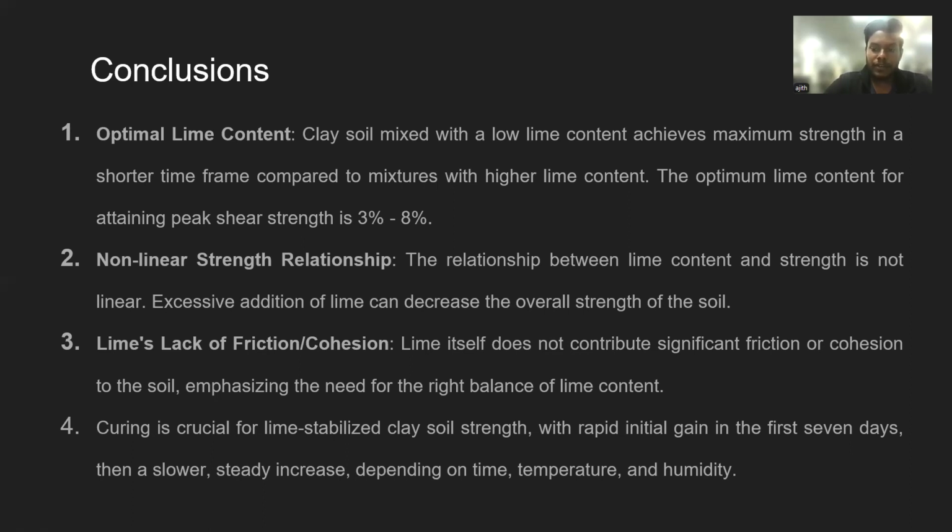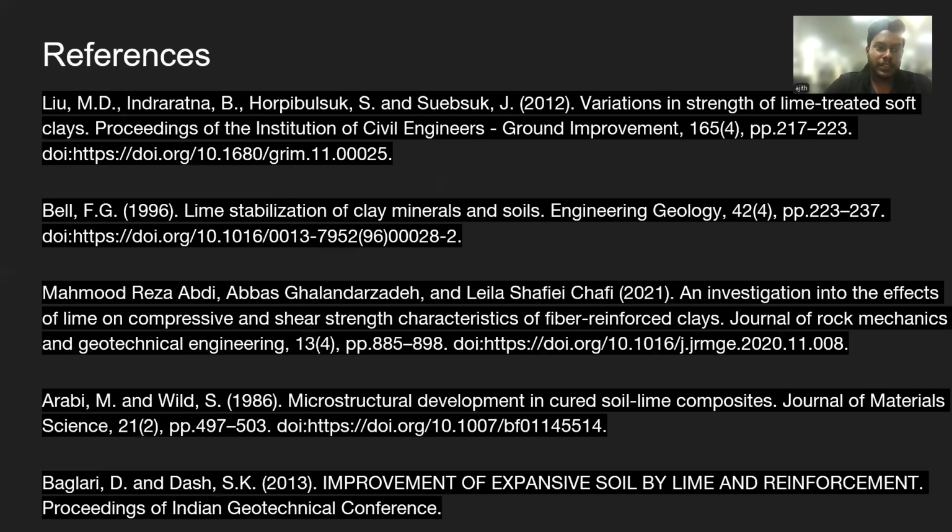Curing plays an important role in lime stabilization, with a rapid increase in strength during the first 7 days, followed by a slower but steady rise that depends on time, temperature, and humidity. Moving on to the next slide.